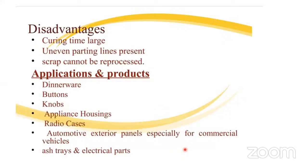Disadvantages: curing time is large, uneven parting lines are present. Scrap cannot be reprocessed. Applications and products. I told you dinnerware sets you can manufacture by compression. All that tableware or dinnerware can be manufactured by this process. Buttons, coat buttons, shirt buttons, you can manufacture by this process.